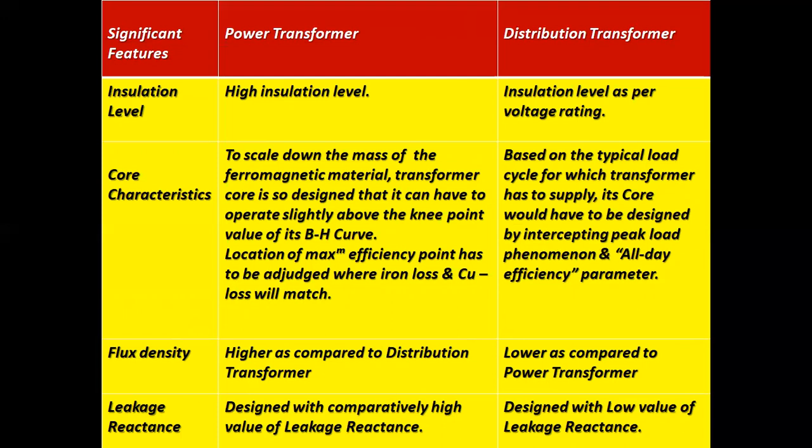So as far as the distribution transformer is concerned, it is based on the typical load cycle for which transformer has to supply. Its core has to be designed by intercepting peak load phenomenon and all day efficiency parameter.